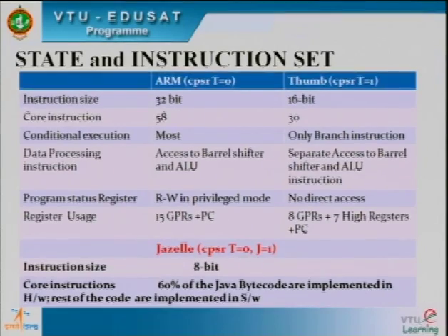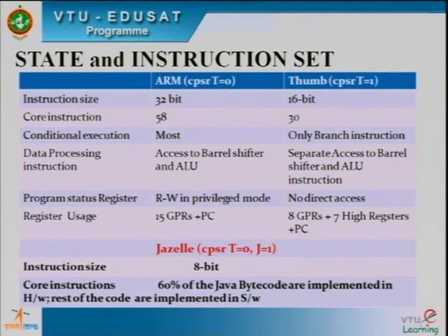Let me say the example, like move on negative, move n. That means only when it is negative I need to move. So some instructions are to be executed only if a certain condition gets satisfied. Such instructions are available or supported by the processor, and such kind of instructions are useful, powerful instructions which naturally decrease or reduce the number of branch instructions.